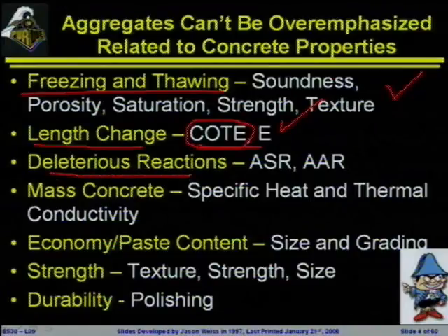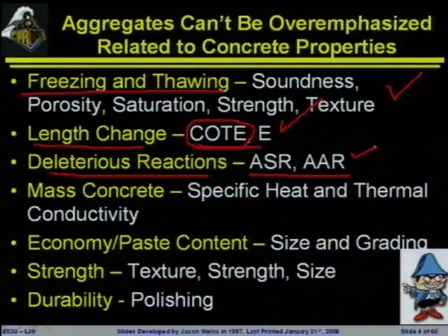There'll be other reactions that can take place. Alkali-silica reaction, alkali-aggregate reaction. Here's where there's a battle going on between the alkalis that are coming off of the cement or coming from the fly ash or coming into the system in fluid, reacting with the silica that's inside of an unstable silica form that could be inside of the aggregates.